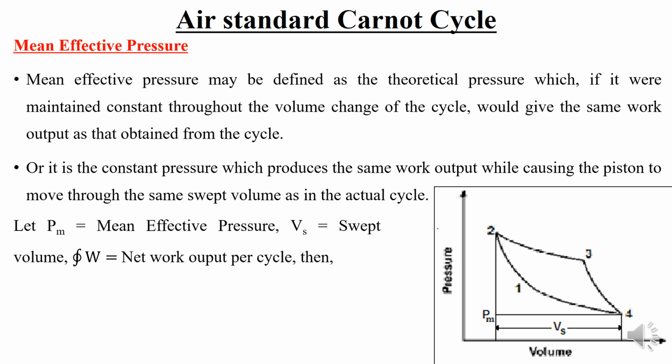That is nothing but mean effective pressure. It is the theoretical pressure, where we assume a constant pressure during the expansion process so as to get the power output. So this is nothing but the average pressure during the expansion stroke, or the theoretical or hypothetical pressure we are expecting during that process, maintained constant throughout the volume change process. So this is nothing but mean effective pressure.